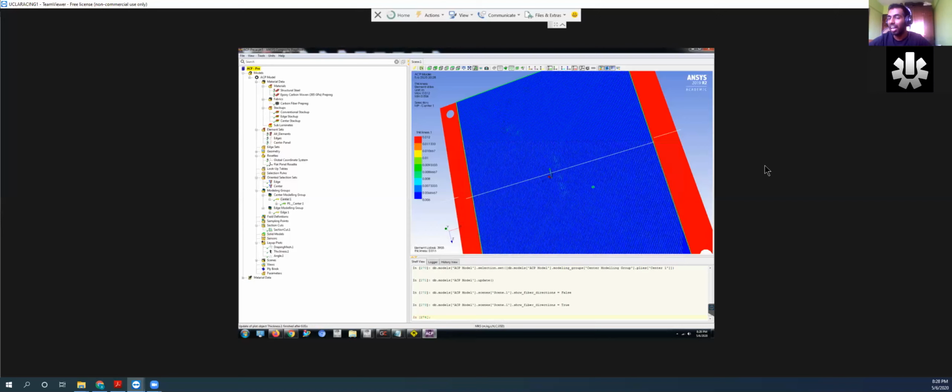So what these lines essentially signify is, if you look at your carbon fiber weave, you'll know, like if you remember, your carbon fiber weave tends to flow in one direction, right? There's one direction that goes this way, and another direction that goes perpendicular to that. So when you're laying up, you always put it like that, right? So it's sort of like you lay the 0-degree direction along the flat panel, and then the 90-degree direction will go perpendicular to that. So just imagine this is the carbon fiber thing that you're laying down on, right?